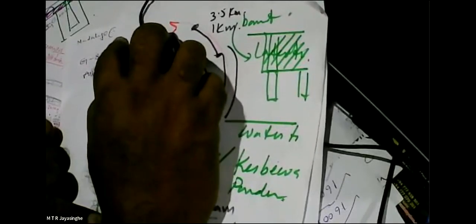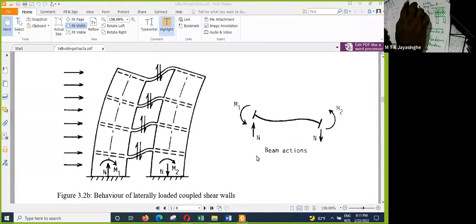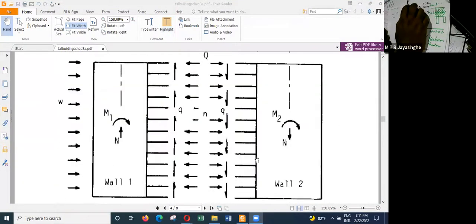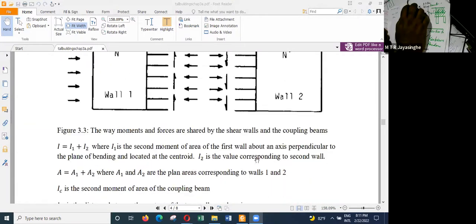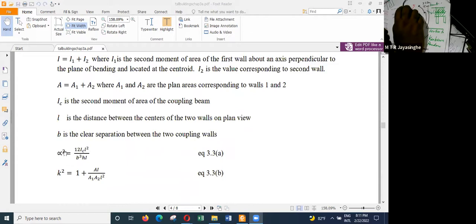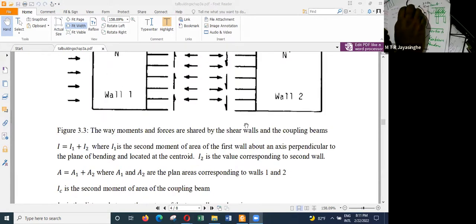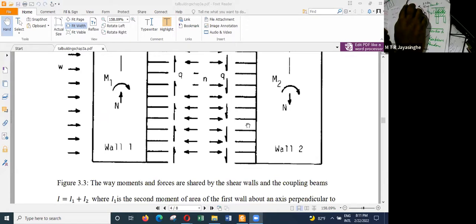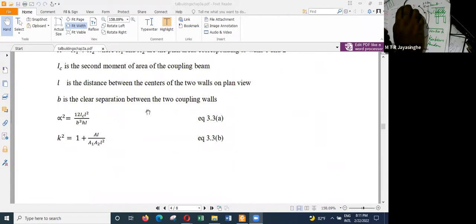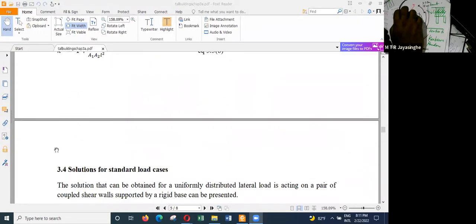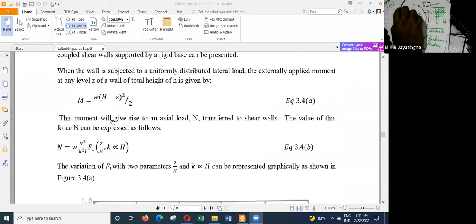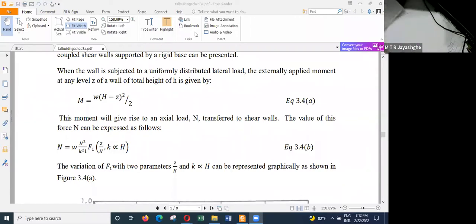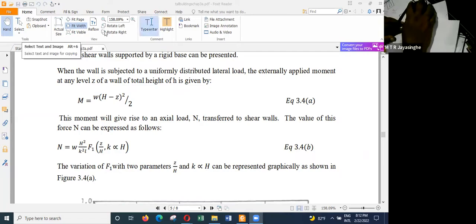And what I'll do is share the screen again. And if you go further down, you can see I will post this. I will share this note with you, and if you can work out, based on the areas, lengths, the second moment of area, all this information of these walls, you can work out some alpha and k parameters, and then you can easily work out, once you know, the moment of a cantilever is given by this. Stop share again.